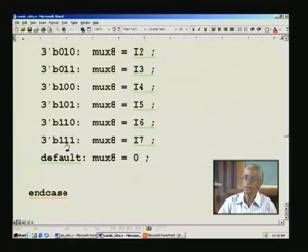and you may encounter X, that is don't cares, or tri-state, say Z, and in such cases you have to account for them as well. So, that is why we put a default here. It is good practice to have a default and take it to a safe state. According to your circuit design, you may consider 0 as a safe state, in some other condition 1 or X or Z, depending upon your real need.